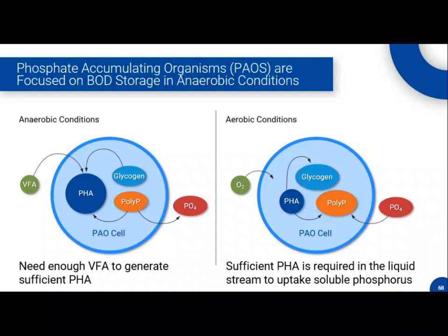That's what our plant can handle, because it's all about hydraulic retention time. If Cruise had a 24-hour HRT in the aeration basins, you could take a lot more of it because you'd have enough time to break it down. That glycol will still slow down some of the rates for your nitrifiers, but if you make your tanks big enough, it'll be okay.